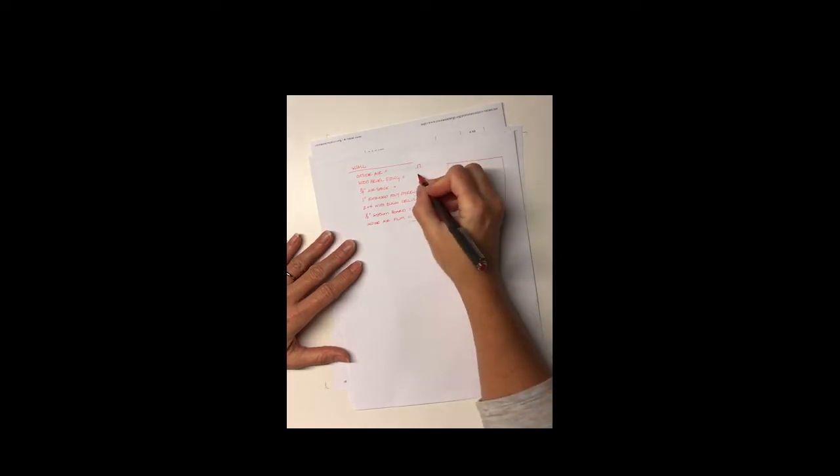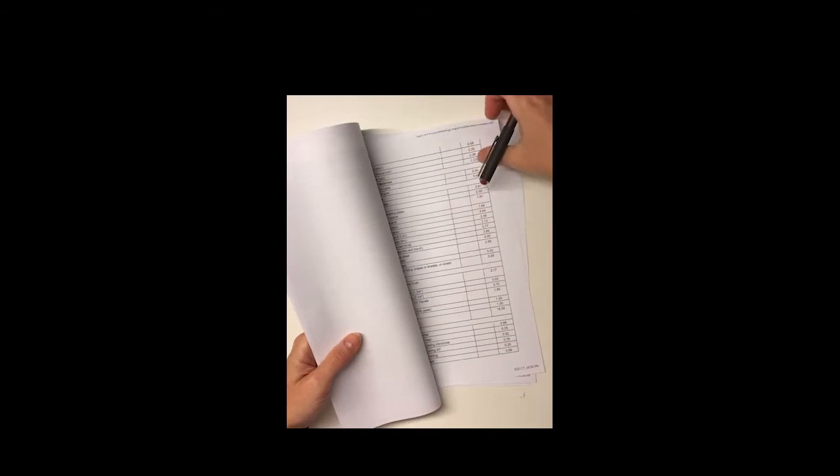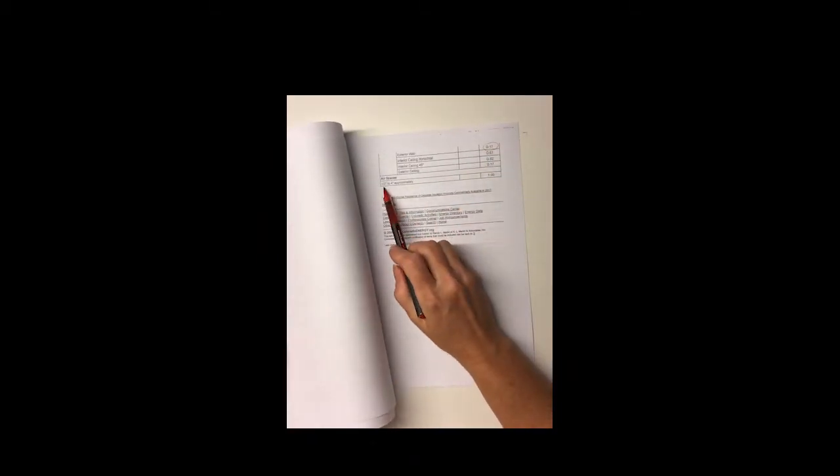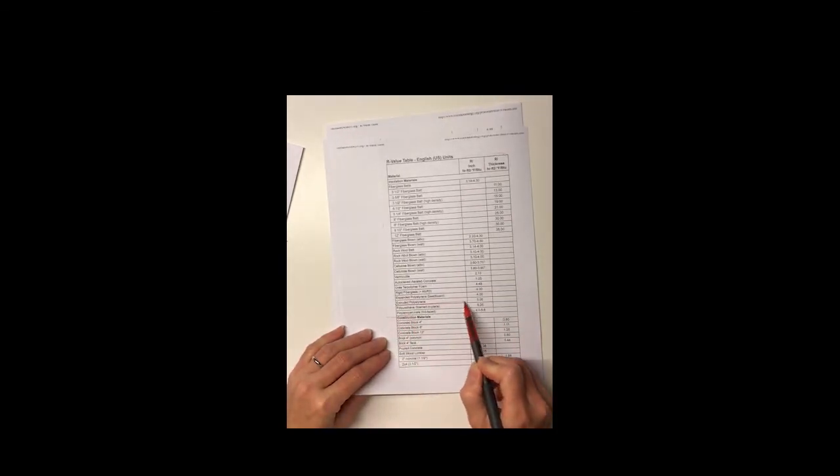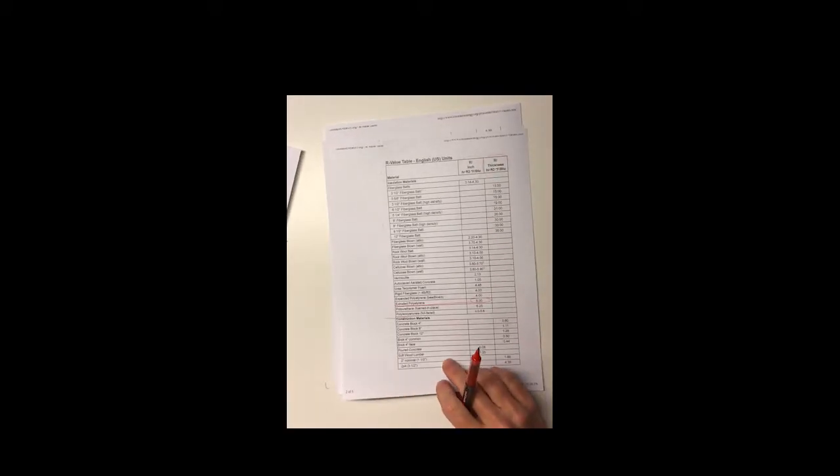So the wood bevel siding has an R value of 0.80, and then the airspace, anything between 1/2 inch to 4 inches, is going to have an R value of 1.0. Then I have extruded polystyrene, and that has an R value of 5. So the R value per inch is 5, and I have 1 inch of that.